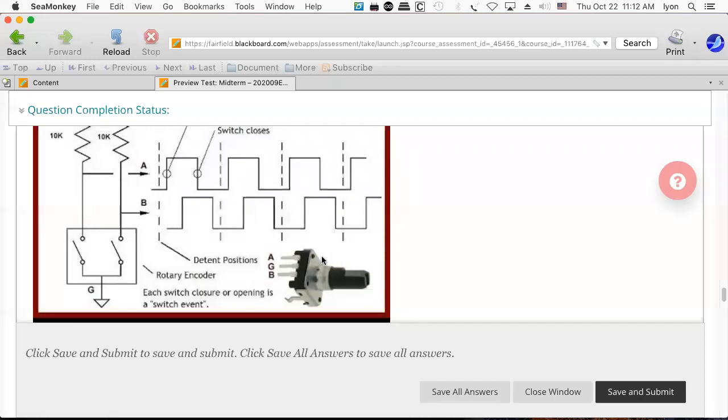You can also use it, for example, on a DC motor, not a servo motor. And essentially, because you've got that feedback available, it becomes a servo motor. So if you think about it, you could take a giant AC motor, not meant to be controlled by a computer at all, from a real clothing dryer, a big quarter horsepower motor, and put a shaft encoder on it. And then you can measure how many times it's turned, and you can servo that motor with an external input.